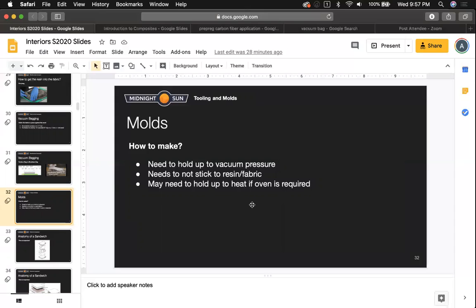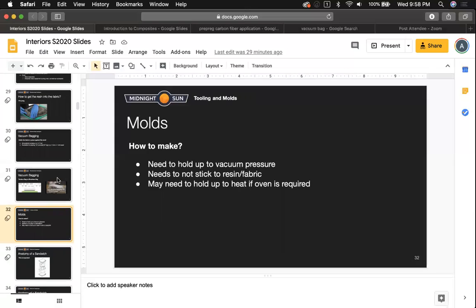We'll make a mold out of a more resilient material, but instead of having to machine it this time, we can actually make that mold out of composite and not use such an aggressive process. We don't need to vacuum bag it. If we don't need such good conformance, we can normally wet it out by hand with a wet layout procedure and still make a mold. And then from there, we use that new toughened composite mold as the actual mold for the final part.